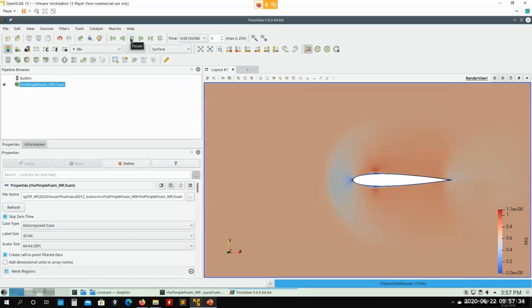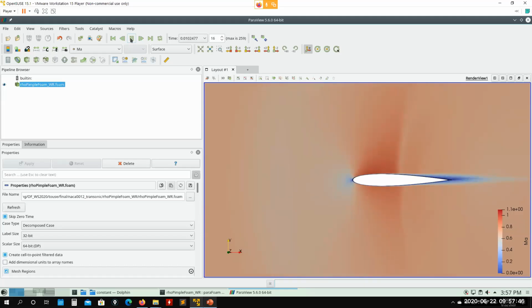So also just to mention that I managed to do also that benchmarking, the high lift, and also that drag prediction workshop. I managed to do also with OpenFOAM. It is very time consuming. You need to run a lot of iterations, but you can do it. But it's true that I think the compressible solver can be improved a lot. But as you play well with your numerics, you can get solutions.